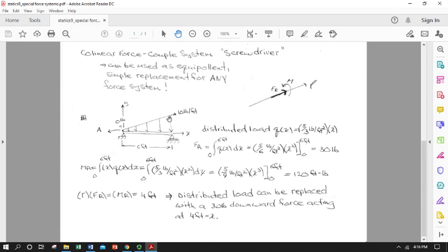here's a typical example of a parallel force system that's taking the form of a distributed load. In this little figure we've got a beam, and it can rotate about a pivot point here on the left, and it can rotate about a pivot point on the right, and it's also on rollers, and this is symbolizing a bearing that is not constrained in the y direction, the vertical direction, or in the x direction. So it can't sink down, but it can float up, and it can move side to side.